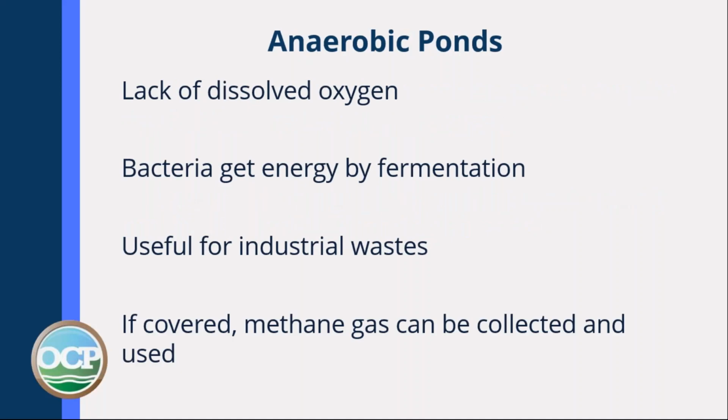Anaerobic ponds lack dissolved oxygen. The bacteria get energy by fermentation of the waste products. They're useful for industrial waste and for use on farms as manure ponds. If covered, the methane gas can be collected and used to power boilers or generators that produce electricity.